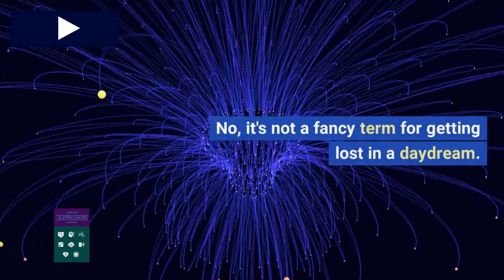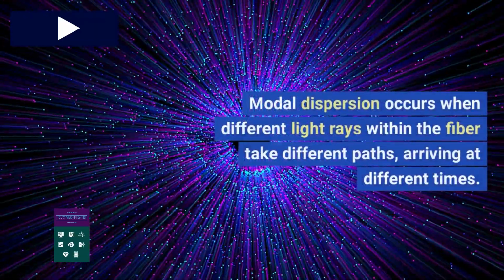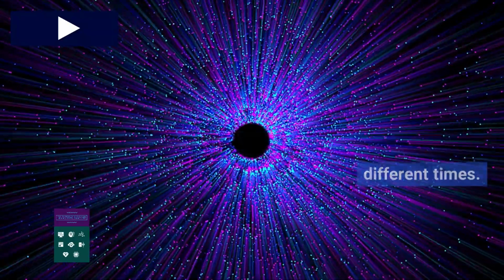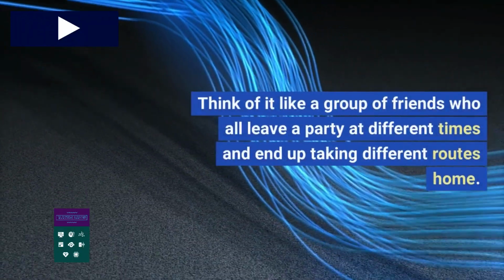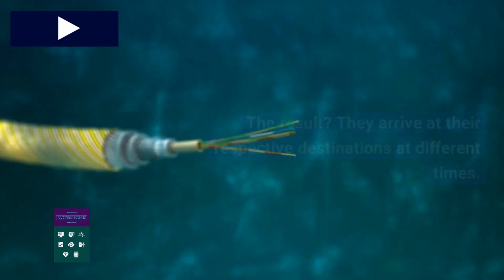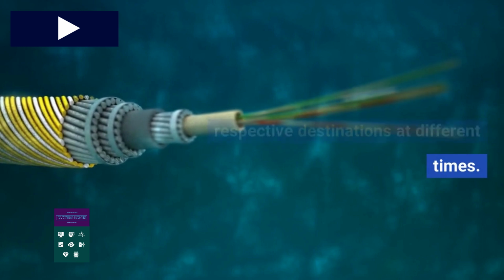Modal dispersion. No, it's not a fancy term for getting lost in a daydream. Modal dispersion occurs when different light rays within the fiber take different paths, arriving at different times. Think of it like a group of friends who all leave a party at different times and end up taking different routes home. The result? They arrive at their respective destinations at different times.